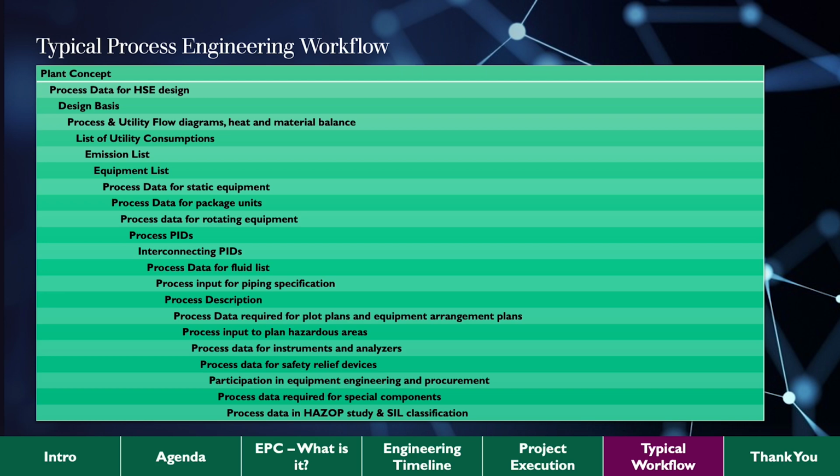So of course, the civil engineering is going to be there. And there are so many questions going back and forth between the customer and you, as an EPC contractor or even an engineering firm, to understand all these details. You're going to need to understand what type of raw material you're going to be using, and what type of impurities are going to be there. Like if I'm going to be using natural gas, there are things that matter in this case. How much sulfur is in there? Is there mercury, for example? Because you're going to have reactors that have catalysts and it's going to impact your process.